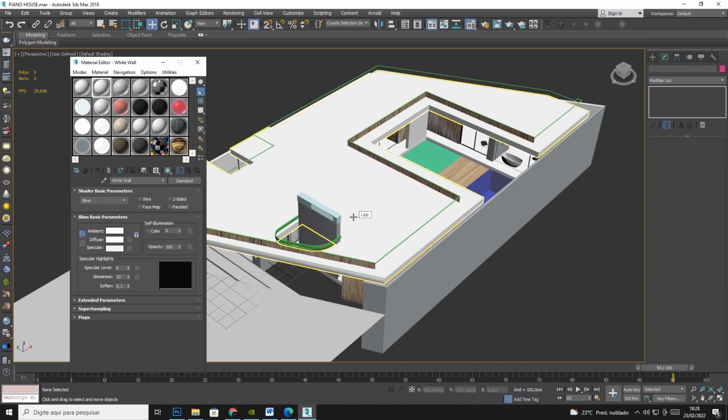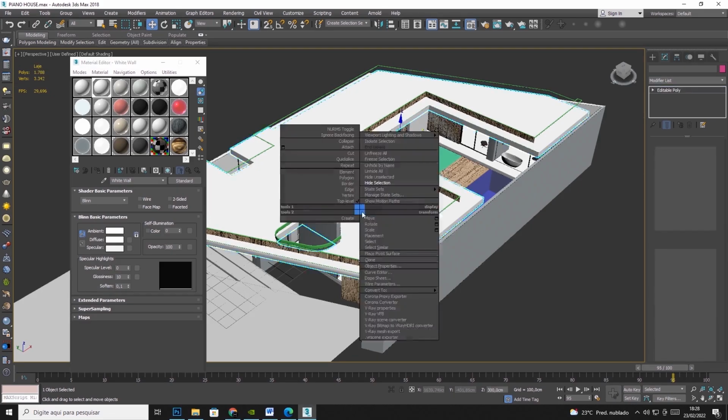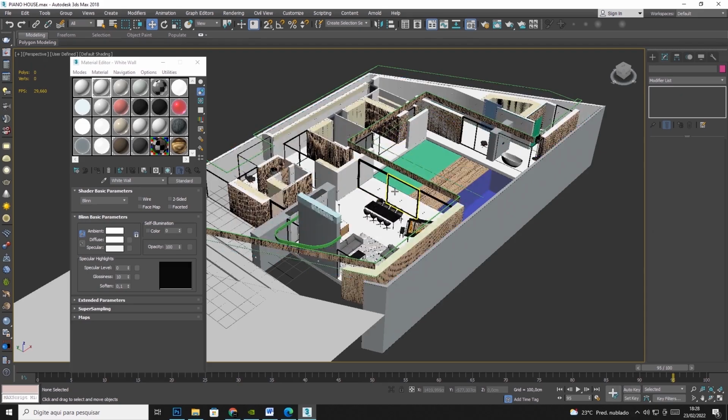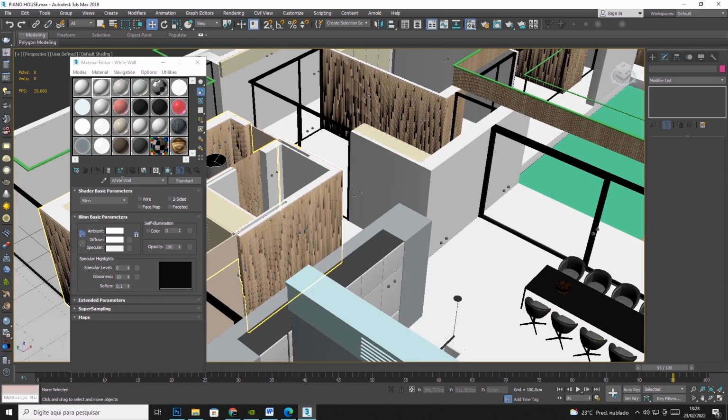This is smart because when I change the material, it will actually change for all the other objects that use the same material. And right button, hide selection. Let's select, for example, the material from the wood. Yeah, great. Standard type material. Let's call it wood. Diffuse here is white, but the diffuse is inactive because we have a map here.